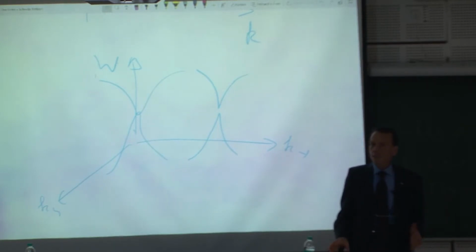So the technology is not yet so matured to have acceptable efficiency. But more or less, you need to have first the generator. You may use power combining. If we now talk about power combining, what do you think could be the main challenge in power combining at terahertz? It is the phasing.